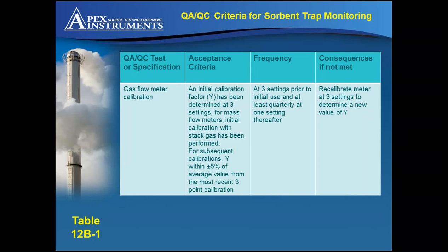The sample volume is much more reliably monitored and recorded using a dry gas meter, so meeting requirements of PS12B are easily achieved against a reference meter. There's no requirement for any kind of bottled gas, stat gas. Again, that's making it easier to audit and calibrate.